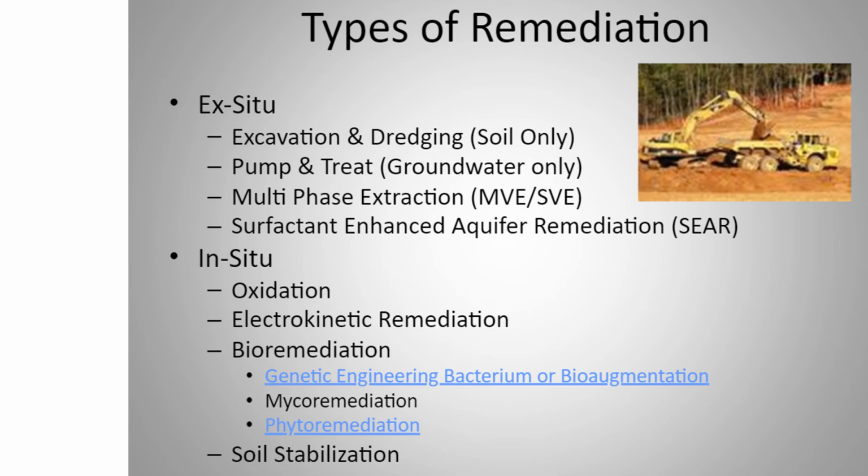So you have a polluted site, you have different tons of soil, and you take the soil away to a treatment plant, or you pump the water away to a particular treatment plant, you treat it there and you release it back. So this is ex-situ techniques, and for in-situ, these particular remediation techniques are applied in place. Wherever the polluted site is, we apply the techniques there.